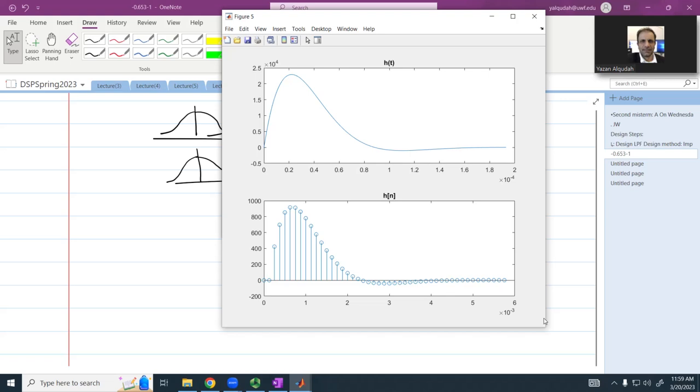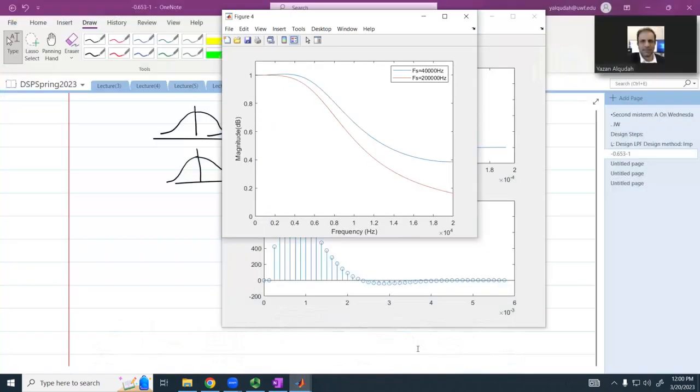Is that clear? So is there a Nyquist equivalent for the aliasing here? Because of the aliasing, you might be failing your specs based on your sampling frequency. That's correct. You might ultimately not be able to meet the attenuation that you have set. Yes, a good point. So after you build the filter, you have to test it, make sure it is indeed meeting the specifications. Make sense?